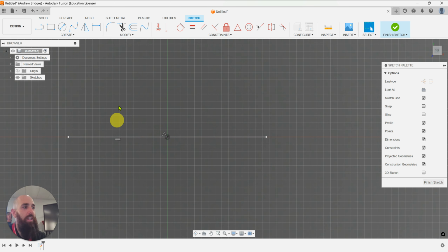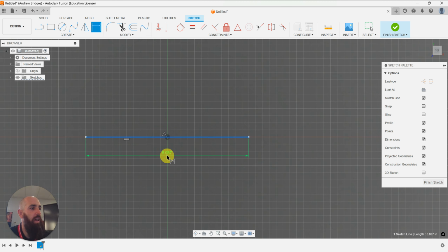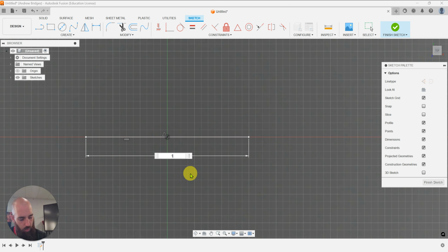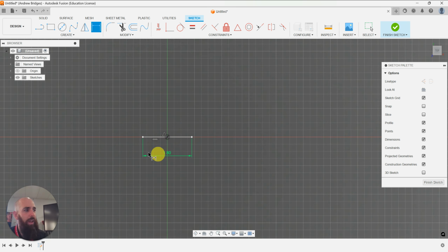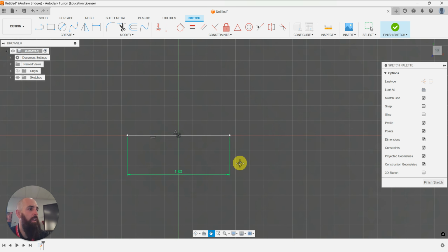Okay, and you'll notice that it turned white. That means it has a place in space, absolutely. What it doesn't have is length. So let's look at our drawing, and we're looking at the baseline of the bottom, which is right down here, 1.8. So let's use our dimension tool and say the length of this line should be, whoa, I was way too big, 1.8. So now I can zoom in, resize it to fit my screen, and I'm actually going to bring that dimension up above.